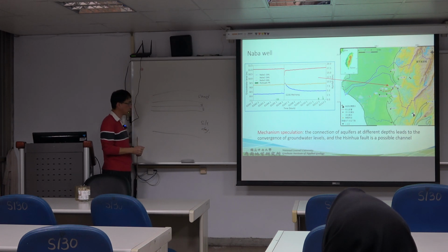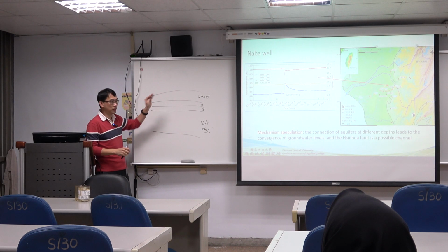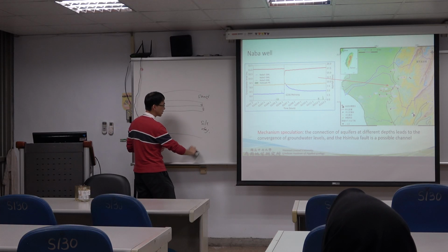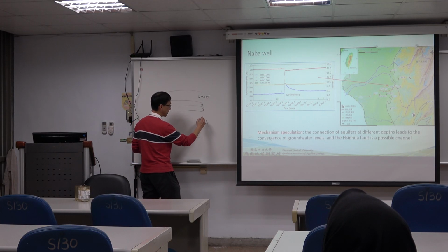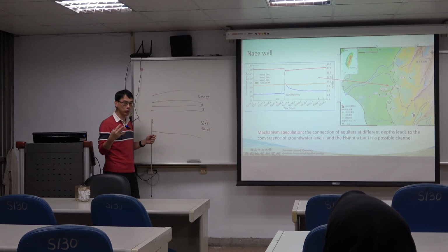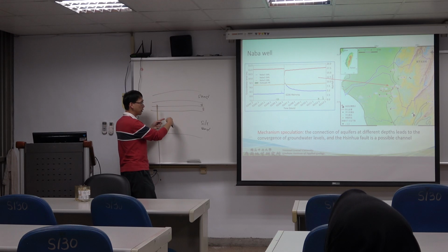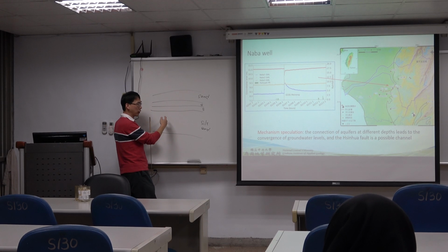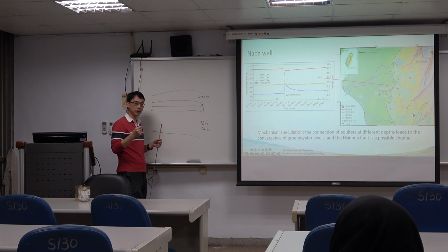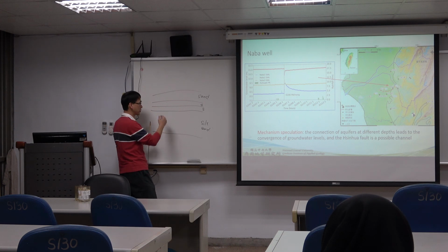Originally the system may be like this, but in some situations this layer could be a seal, or fine sand, maybe silt or sand. When some earthquake triggering makes this area liquefied, it induces increased water pressure, right? The water needs to find a place to escape or to decrease the high water pressure. So they might induce this kind of shape, or sometimes this kind of shape.